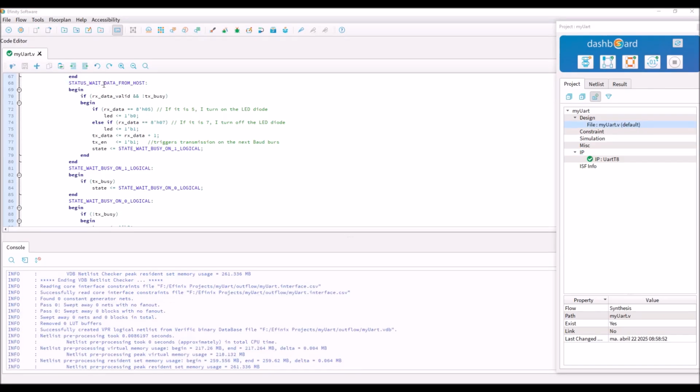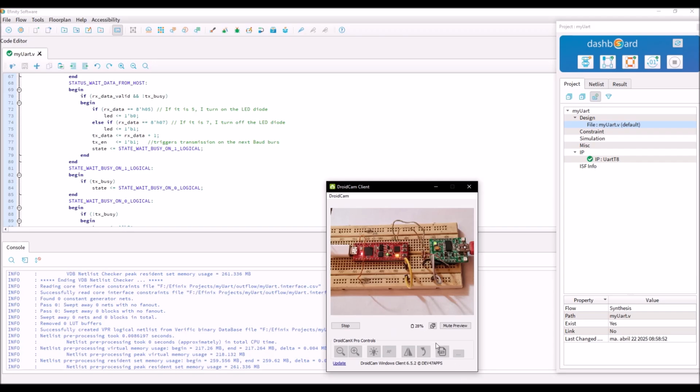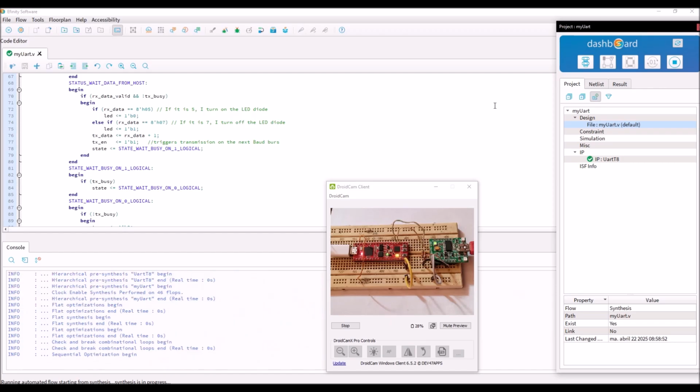Here is the Antfire on a protoboard, and you can see that it has the project from the previous video, which I've linked in the description. On the right, there is a USB to UART converter, and the transmit and receive lines of both modules are connected through 330 ohm resistors, which I added for safety to prevent a short circuit between them in case of a possible misconfiguration or connection mistake.